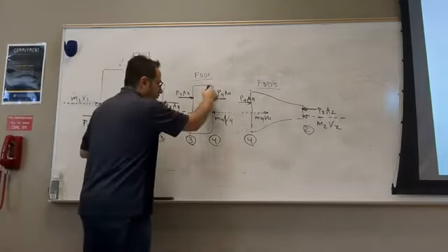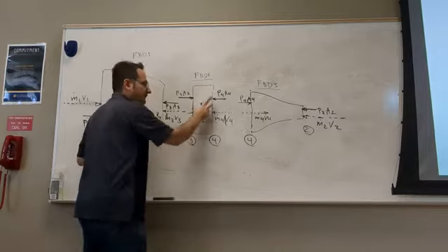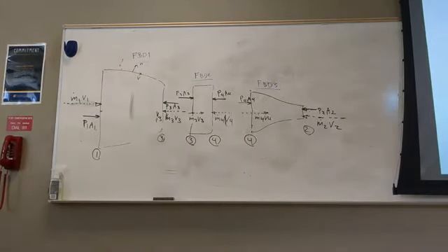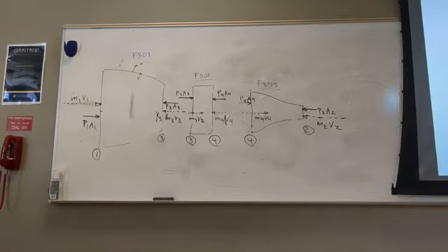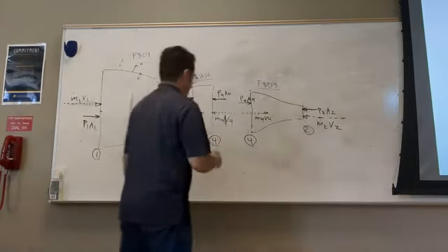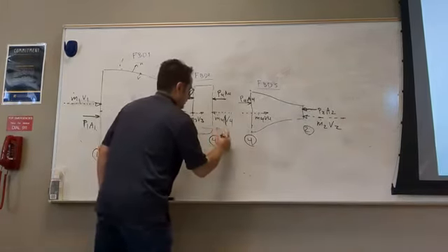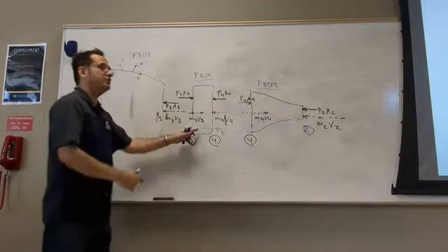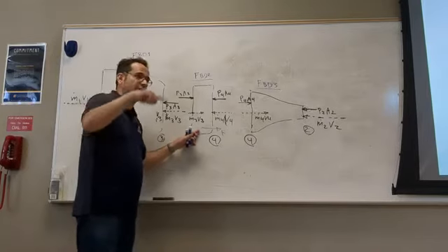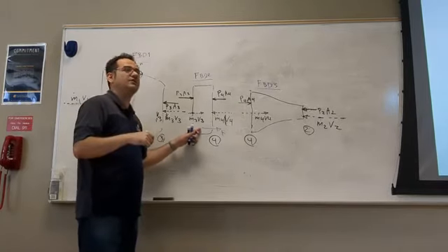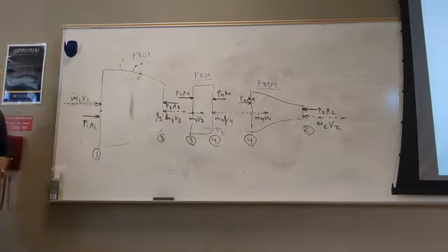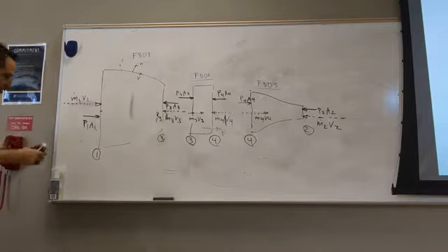What's the direction I should put on the FPD? This is the flow, not the blade. This is the FPD for the fluid around the blade. What direction is the force put on it? To the left. Right, because this blade is pushing it to the right. Now, if I wanted to take the blade as my system, what would the direction be? Just like the nozzle problem we solved before. Okay, now we're ready to write equations.